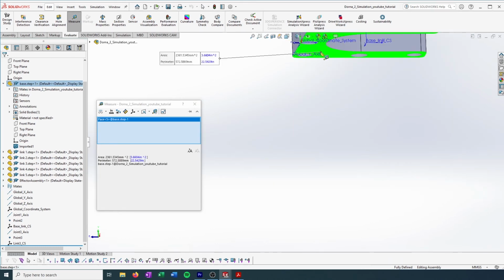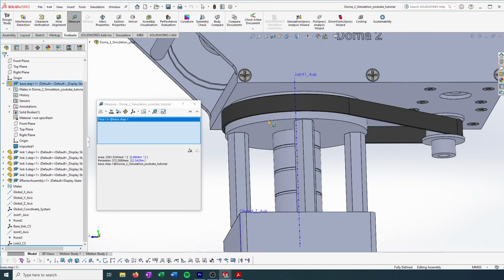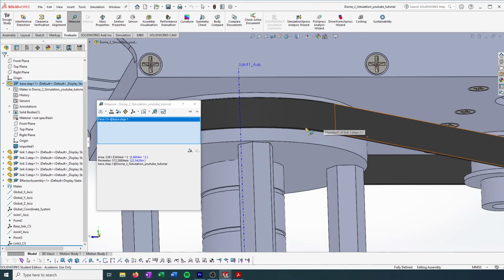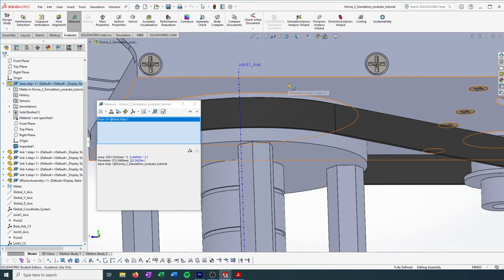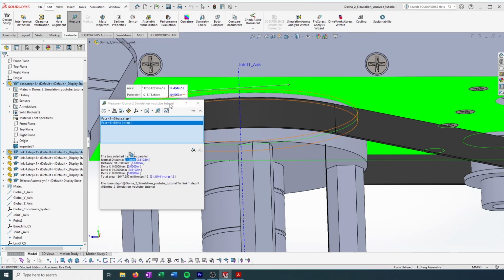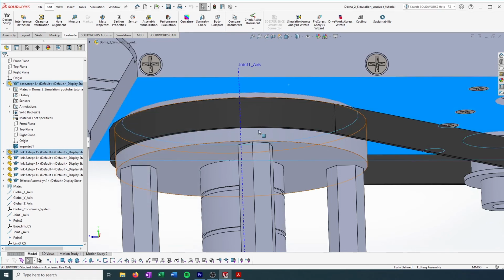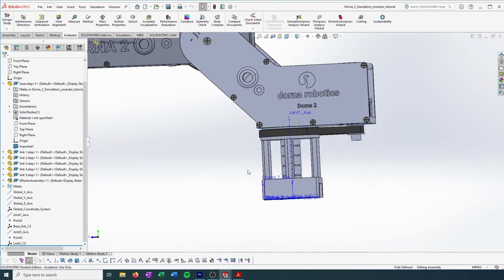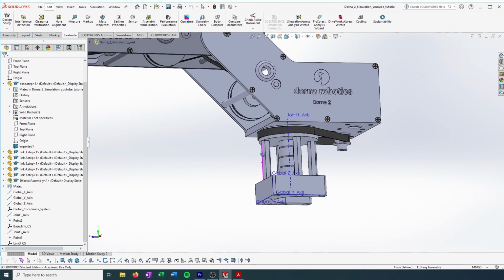And then see what height. I remember this from before. It's probably like 90. It's right here. Yeah, see, it would be preferable if I could get a face somehow. Let's do this face. 91 millimeters. So I'm just going to say for this purpose it's 90. It can be okay in some instances for your collision models to collide, but I would generally avoid it if you can.